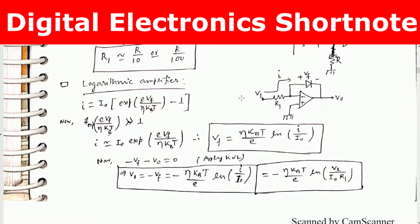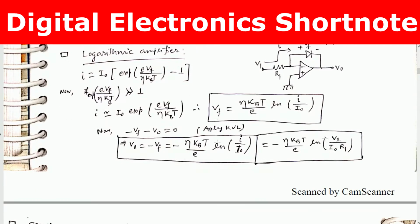Logarithmic amplifier. I equals I naught into exponential of e Vf by eta kB T minus 1. Here in the feedback portion we employ a diode, and it converts the circuit into a logarithmic amplifier. If exponential of e Vf by eta kT is much greater than 1, then I equals I naught exponential of e Vf by eta kT. We neglect the one term, and we get Vf equals eta kT by e ln I by I naught.